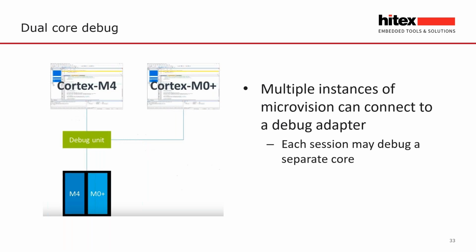Now we've done a couple of projects using multi-core microcontrollers, and it works, but you have to be a little savvy about how the hardware is constructed underneath. There also you have to generally follow a sequence to bring up both processors correctly. So there's a bit of synchronizing and managing both of the underlying devices, but it does work and it's achievable. But do go in with your eyes open when you're going to use a multi-core processor.